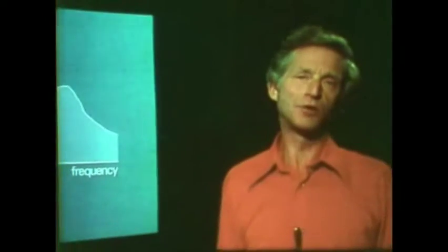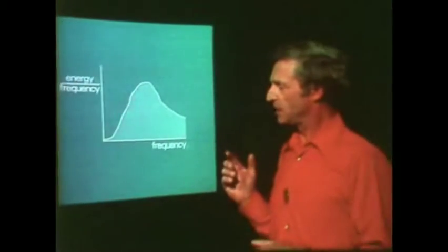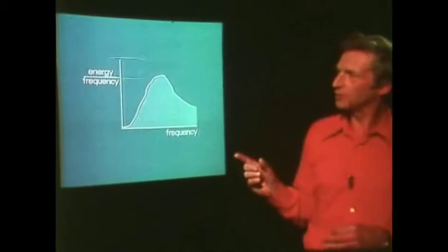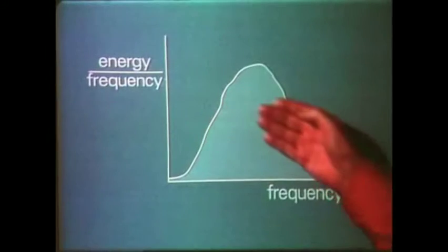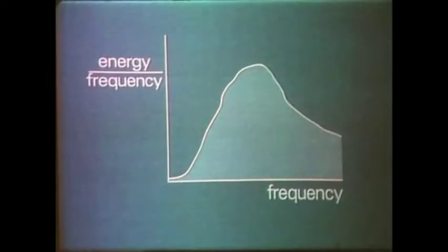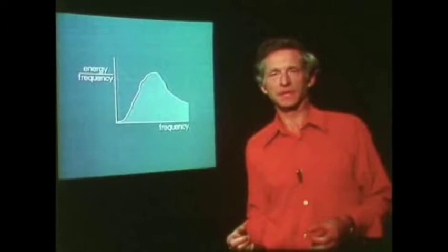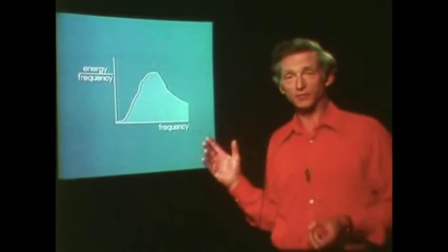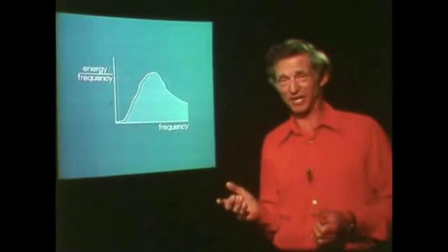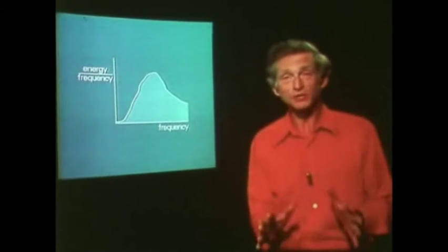And once you've analyzed all the heights and frequencies, you can then calculate the energy per frequency and plot an energy density spectrum that looks like this. I want you to realize what it is that's being plotted. You've got energy over frequency plotted against frequency. And so the area under the curve represents the total energy carried by the waves. So here's how we can represent the energy of the sea surface after analyzing the real wave groups into their components.